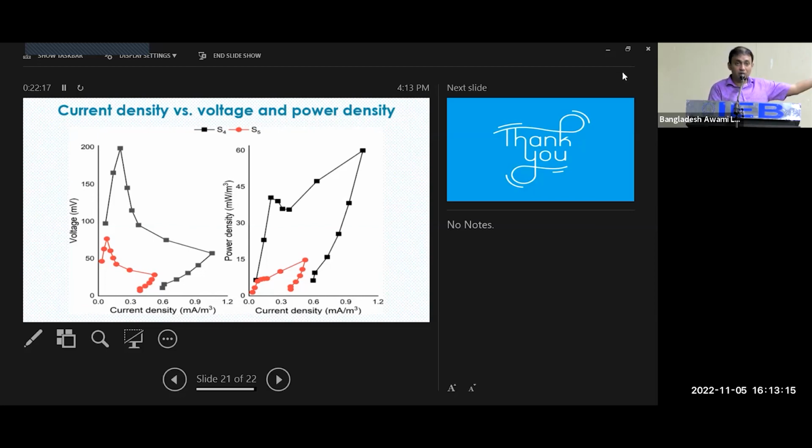But if you operate this continuously, for example, 7 days a week without any rest, you will find a significant decrease of dissolved oxygen. Maybe you will see 0.5 milligram per liter because oxygen is not entering due to saturated media. That's why I was telling you that you need to follow a schedule, 2 days of feeding, then resting. If you continuously feed sludge, it won't get time to release the water. So sludge will accumulate, but that will be wet sludge. And again, the bed will be anaerobic. So the aerobic reaction, for example, nitrification, won't occur. You won't be able to remove nitrogen. So this has to be maintained.